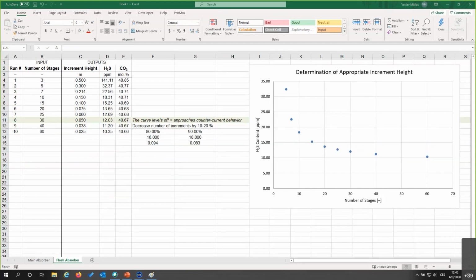So Tanya was asking if I have to use any part of HETP depending on each type of packing. No, absolutely. This mass and heat transfer model is completely independent of the whole concept of HETP. So the increment height, I think that's something we kind of covered as we went.